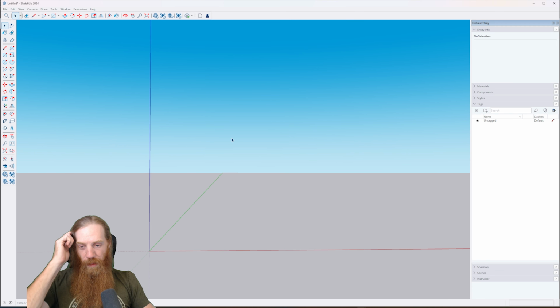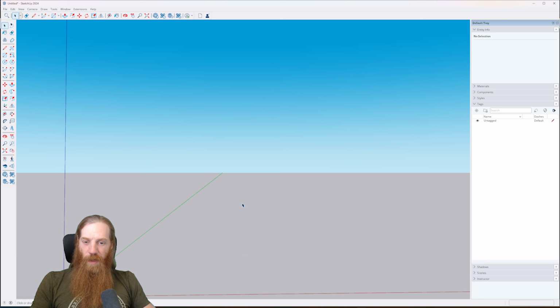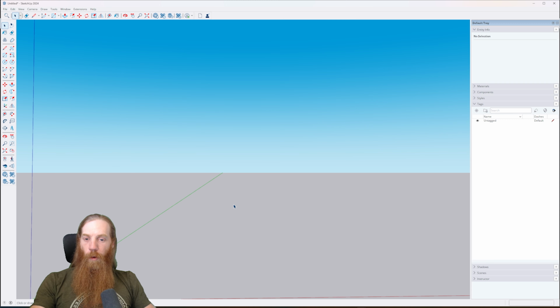So those are the basic movements of how you're going to control the camera view, and that's really everything you need to know. You also zoom in or out with the mouse wheel. We'll go into that a little more later, because zooming can be a little confusing at first. It depends what your mouse cursor is on. If your cursor is on a part of the model, it'll zoom into that model, and it won't go past whatever your mouse is on.